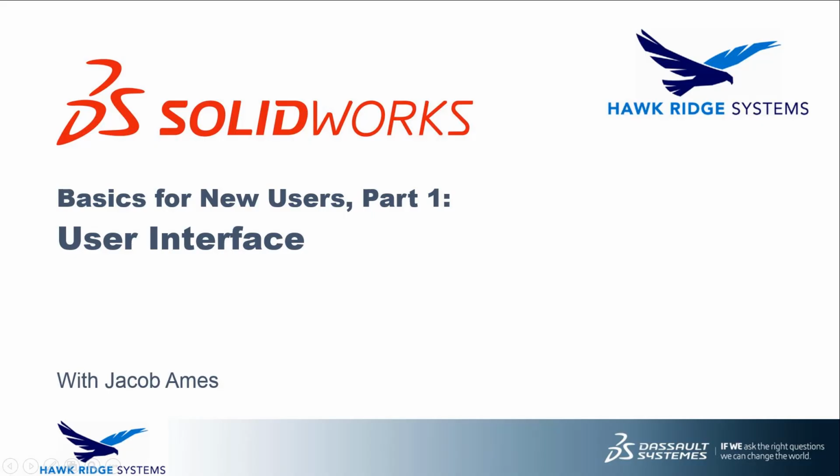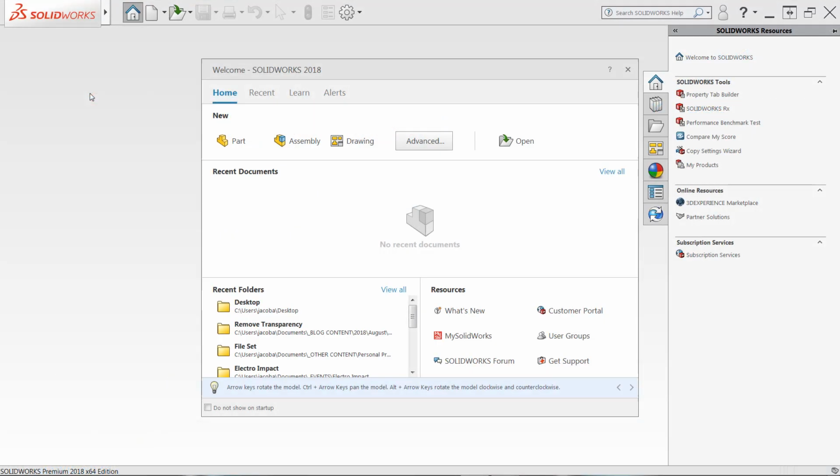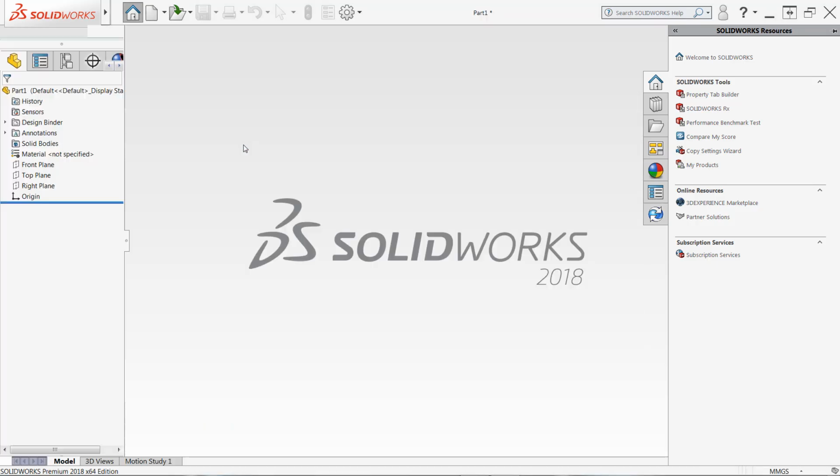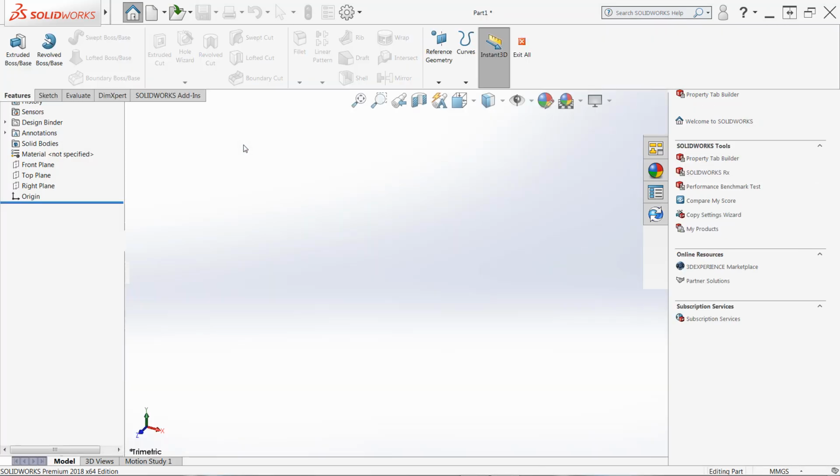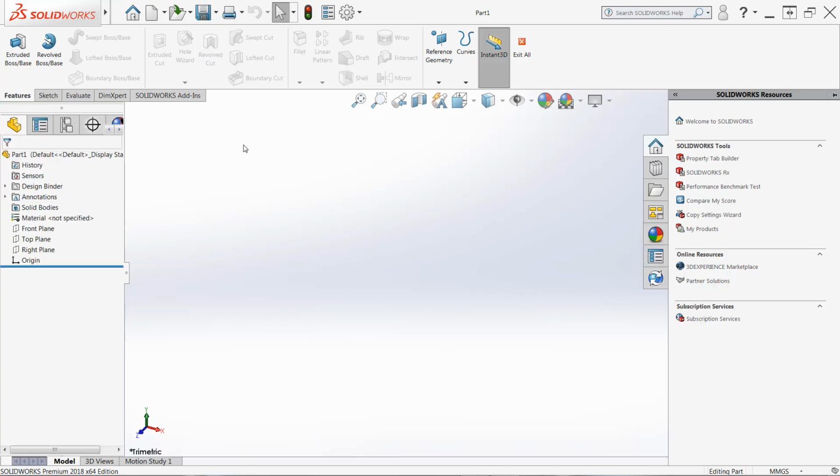In this video we'll be covering the basics of the SOLIDWORKS user interface, giving you the tools and understanding that you'll need in order to be prepared for your first design, tutorial, or training class. Now when SOLIDWORKS initially starts, you'll be presented with a welcome dialog if you're on SOLIDWORKS 2018. If this is the case, to get started, simply click the Part button in the New category. This will open a brand new document, and all the elements of the user interface should be revealed at this point, so your interface should look something like mine.